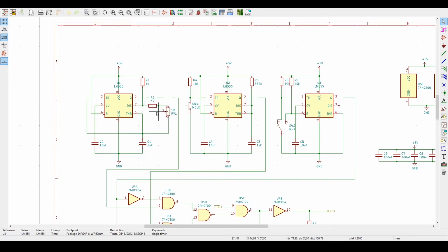It's a potentiometer. And the internal circuitry of the 555 timer has two comparators at 1/3 and 2/3 of the voltage it is applied to, and it keeps charging and discharging the capacitor between these two boundaries, 1/3 and 2/3 of the voltage.